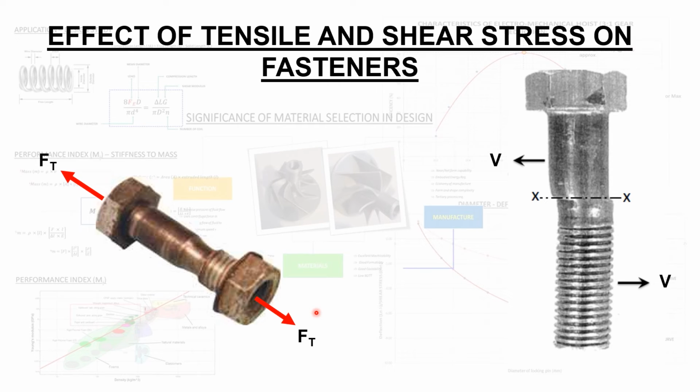Now, as the component stretches, particularly with ductile materials, you have what's called localized necking, and this is due to a lateral strain that is causing some shear effect, which will eventually cause the bolt to break or cut.